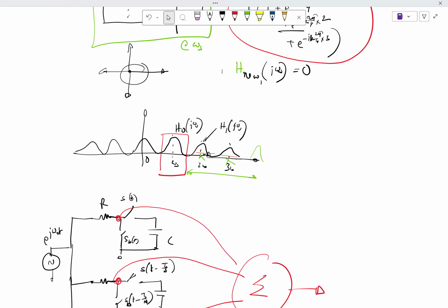The good thing about an LPTV system is that you can make sharp filters. But because it is based on periodicity, you end up having things at some harmonic frequencies. If we cannot get rid of harmonic frequencies totally, what we can at least do is make them far apart. Having one kernel makes them close by, 1 omega s apart. Having N of them makes them appear N omega s apart. So that's the motivation.